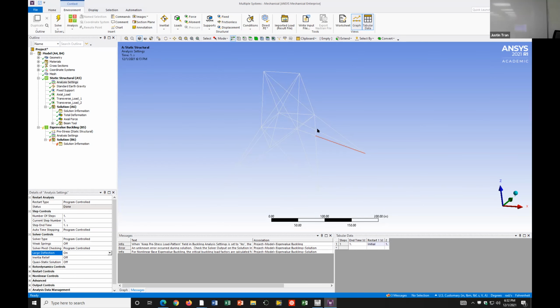Oh, yeah. So you see, when you apply a load that's really high at once, then you're going to have failure in multiple members. So for the lower ones, you only get failure in one of these. But for higher ones, you get multiple failures. Then you're saying that this only highlights the one that will fail first. Exactly. Could these other guys be buckled as well? They could, but not nearly as much as this one. So this is the one that's actually going to crumple and fail. And this one is crumbling just because of location. Exactly. Because of this configuration of forces, this is the one that's experiencing the most compressive forces. So that's the first one.